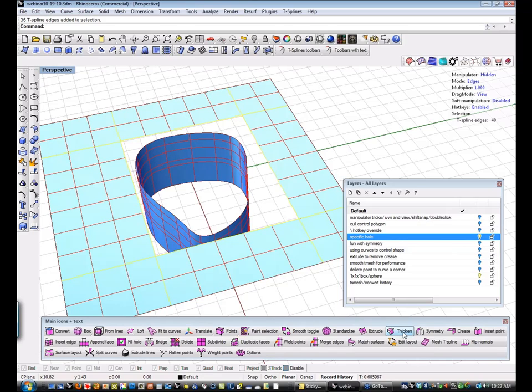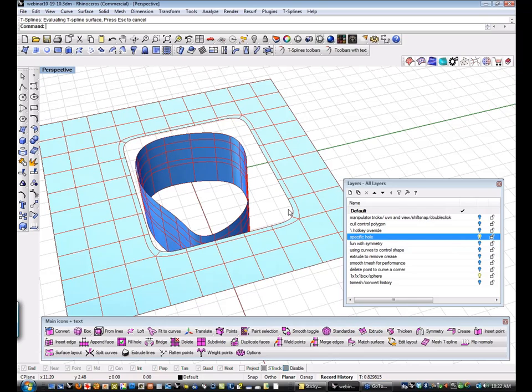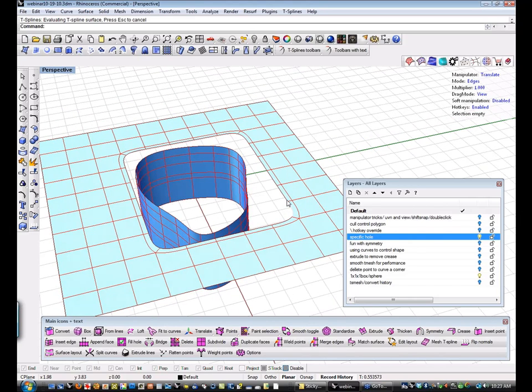Since I'm extruding, I'm going to extrude an extra ring of faces, an extra edge. And since extrude only works on exterior edges, it doesn't matter if this stuff is already selected. I can just hit the extrude button. It'll deselect the stuff that doesn't work, add an extra ring of edges in here, and I'm already set up to bridge from this to this.